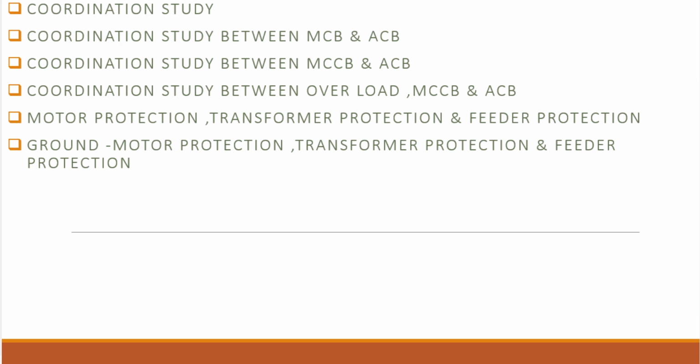As an example, I will explain how you can adjust and what is the value for thermal overload protection function, excessive startup protection function, short circuit protection function, and the ground fault protection function by using a protection relay from ABB and the built-in ETAP software. After that, I will talk about transformer protection. In this part, I will explain how you can adjust and what is the value for overcurrent protection function, short circuit protection function, and earth fault protection function.